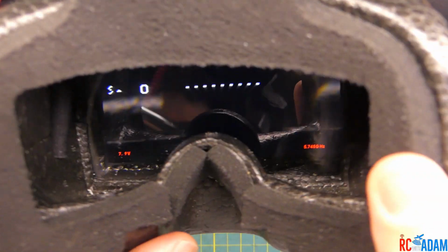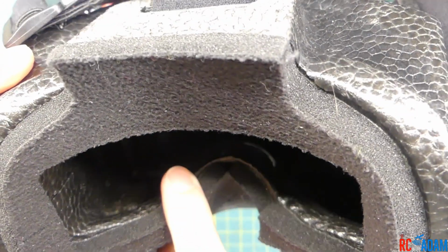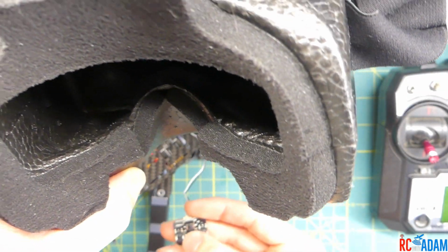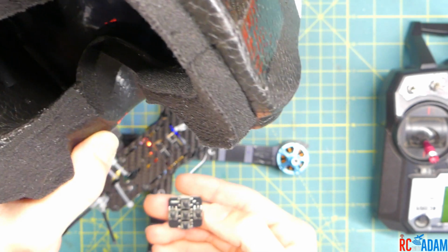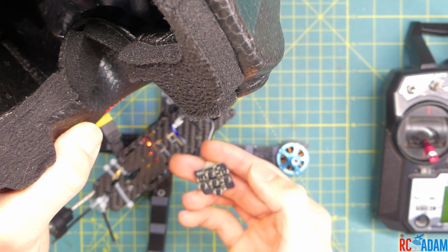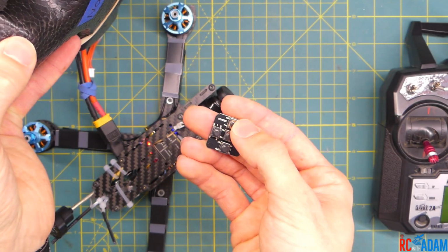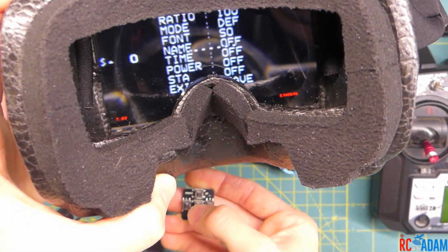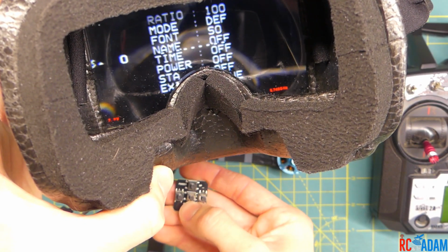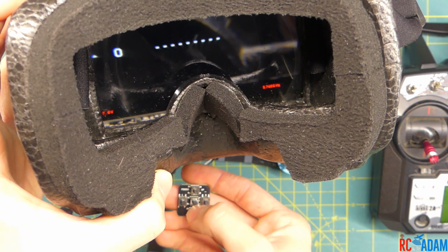So what I do want to show you here is, you can see there's our OSD that we put on there from Betaflight, and I've already taken off the OSD that comes on here automatically. Now, if you want to, the way to do that is you just get your little toggle thingy, and you just press the up button, press and hold, and then you can see that this is going to pop up, and then you just scroll through the menu and you turn everything off, and then you hit exit and save.